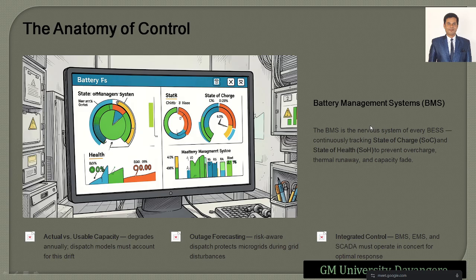C rate I have already explained in one of the early morning classes. Okay, how you calculate the C rate, right? So based on the C rate only you can define the 4C charge. For example, 5C charge, how fast it gets charged. Okay, how the battery can get degraded, right? Fast charging will lead to less survival time for the batteries, and slow charging will give more survival of the batteries, right? So that is how it is going to kill your electrodes, causing cracking in the electrodes. The faster the charging, what happens to us, it tries to destroy.